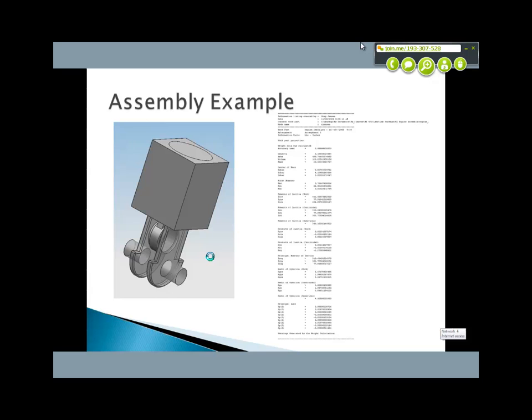If you modify the design too much, which happens in real life out in industry, if you remove material, if you shave off portions of a body, and you get the mass properties where you like them, you then need to think about redoing the finite element model to make sure that you haven't weakened the structure or the assembly to a point that it can't perform.